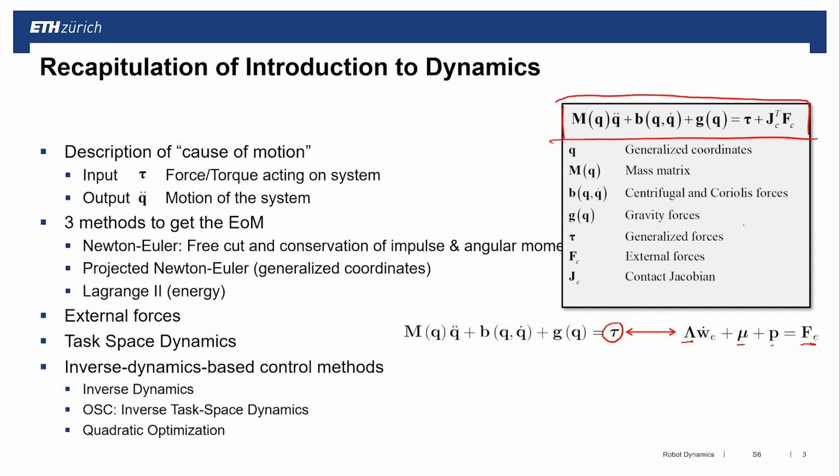And in my eyes, this is a very important element for you to understand: what we're doing in these joint space or task space inverse dynamics problems is nothing else than optimizing the torques, optimizing the motion, such that a number of linear equalities hold.